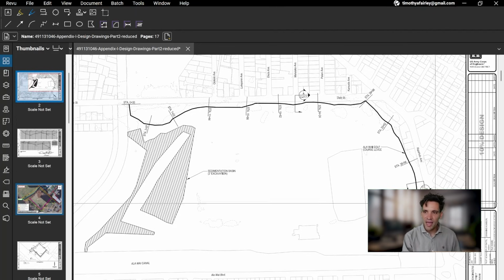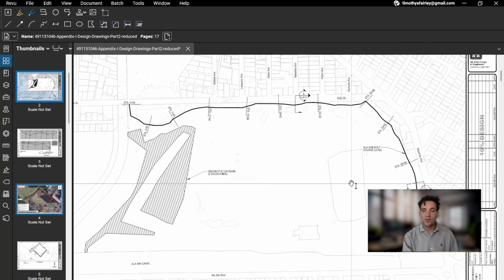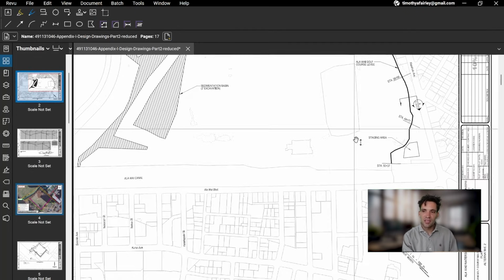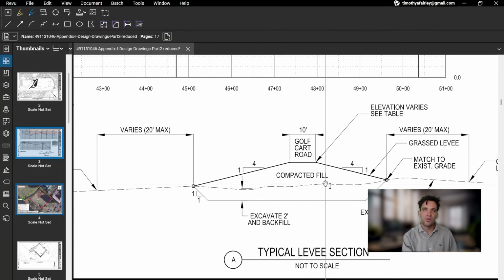Then all the material we excavate out of this, how does this match the volume of imported fill we need for our berm? Because fundamentally, the big assumption here would be we can reuse this material to actually construct this compacted fill for the berm.